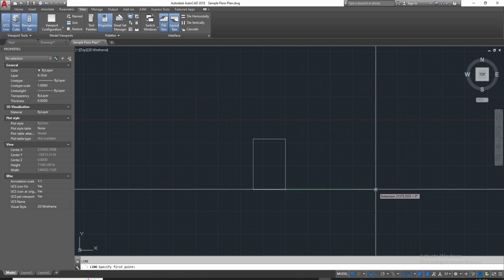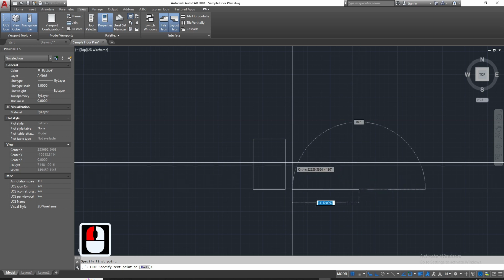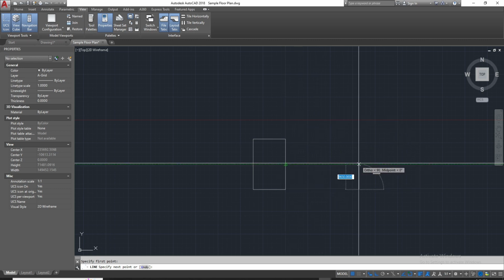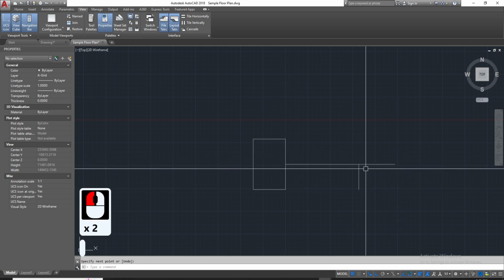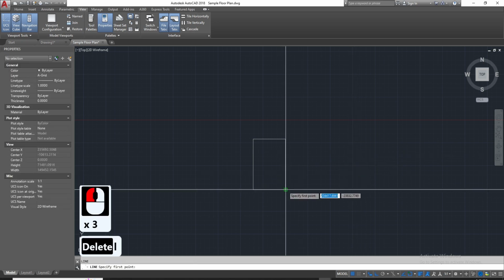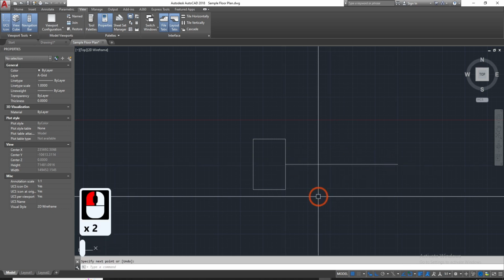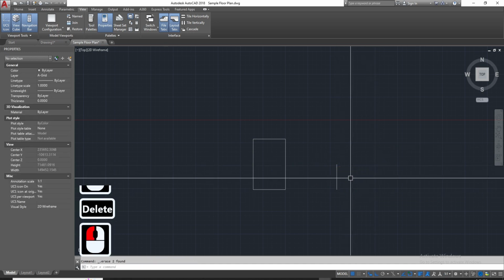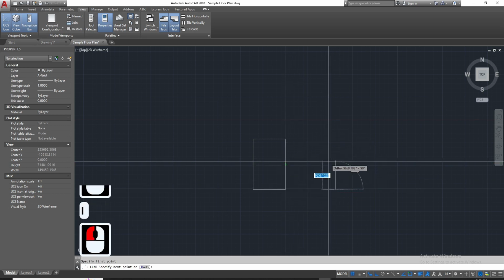See this another example, where I want to make a line that is aligned to the bottom and to the center of the rectangle. And of course, you can also make reference lines like this, and delete them afterwards. You can use object snap tracking in so many situations as you make your plans. Just remember you have these features.